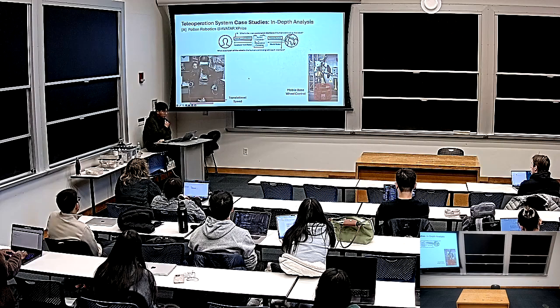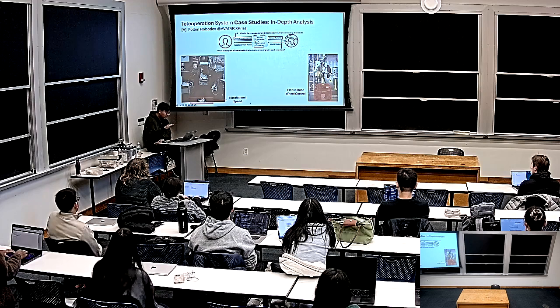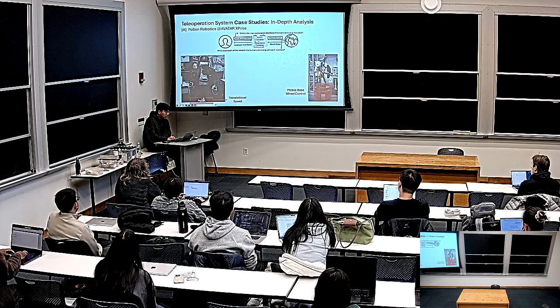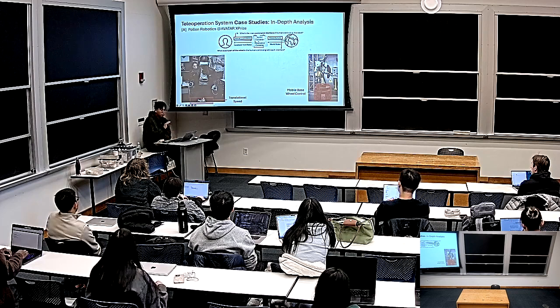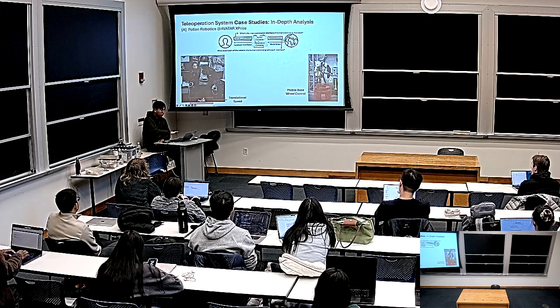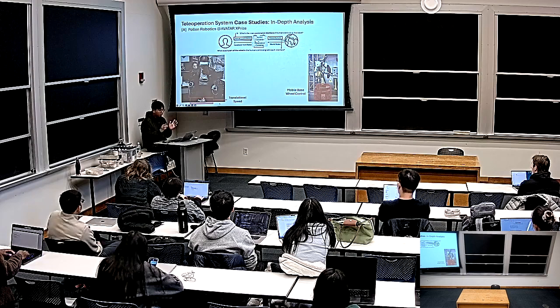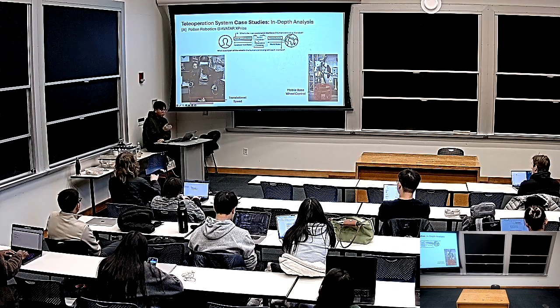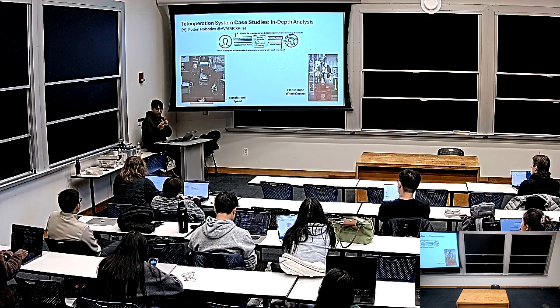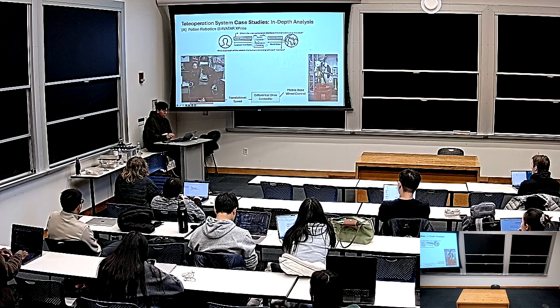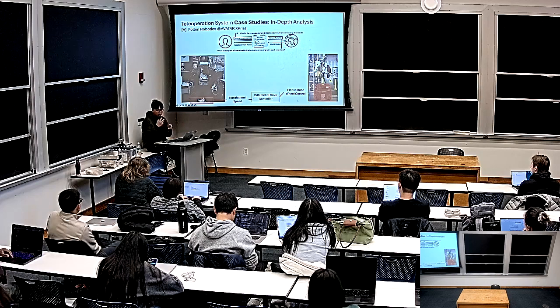And as you can see in the video, all these robots are mobile, so they have to move around in a spatial map. This teleoperator system uses a pedal to control those mobile movements. The pedal commands the translational speed of the mobile base, and the robot is actually expecting a control that is wheel velocities. If there are 2 wheels, then by controlling different velocities of different wheels, they can move around in the spatial plane. So how do they convert this translational speed to a wheel speed?